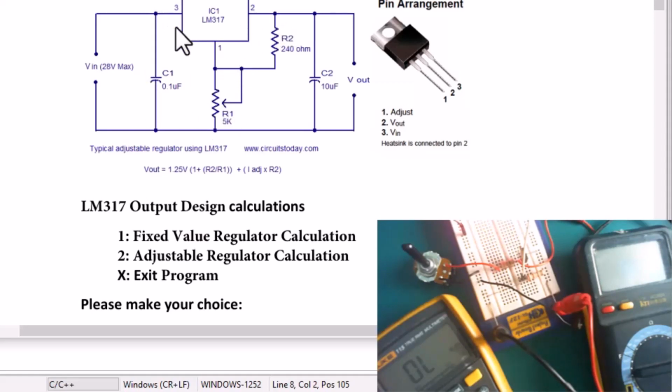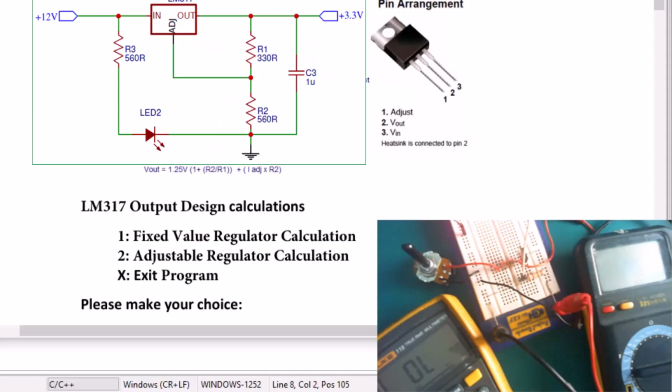So what this means is, to minimize the waste, or to at least get a good enough efficiency, your input voltage must not be very high if you are going to be scaling it down to a very low output voltage. In other words, the difference between the input and the output must not be more than 3-4 volt, otherwise you will have a bad efficiency.